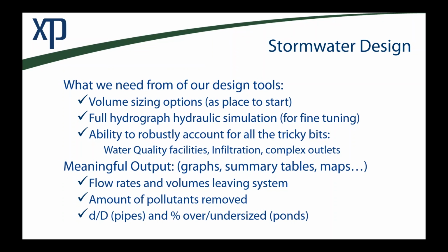And very practically speaking, when we're designing, we need to know a couple of very specific items. One would be perhaps flow over capacity in the pipes. So when you're sizing pipes, the best way to do it, I guess in my experience, would be to look at the flow that's being pushed through a pipe and then look at the capacity of that pipe. And if you find that the flow that's being pushed through there is greater than the capacity, well, that means you're probably surcharging that pipe. And we don't want to do that. So we'd have to upsize the pipe until the flow through it is less than the ultimate capacity that a pipe can carry. So that's one way you could really quickly and effectively size a pipe.